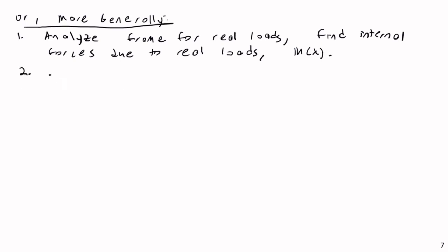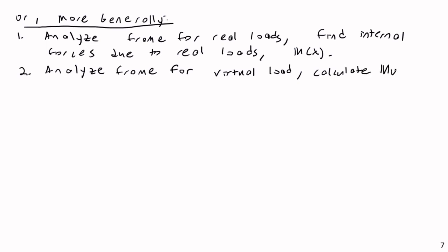2, we'll analyze the frame for the virtual unit load. I'm just restating what I've looked at previously, but in a more general, concise form. Analyze the frame for the virtual load, placing the virtual load at the location where deflection or rotation is desired, and calculate the virtual moment as a function of x for each member.